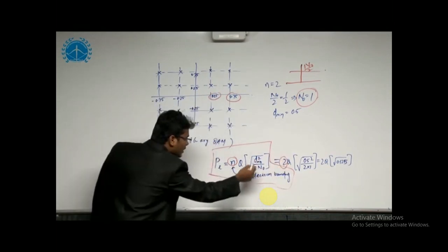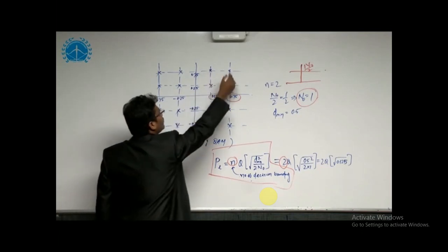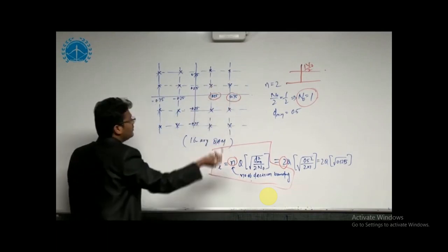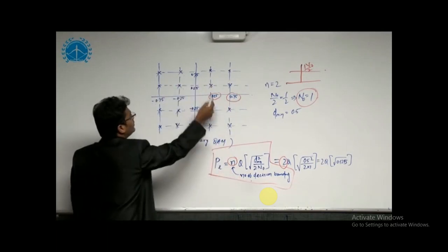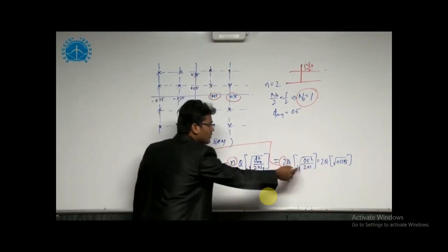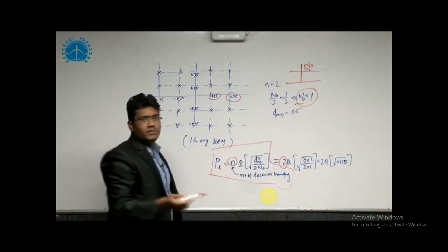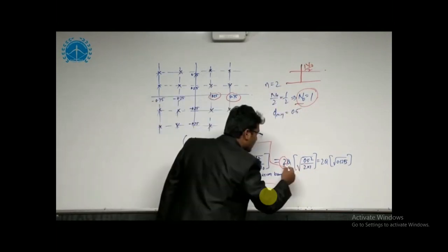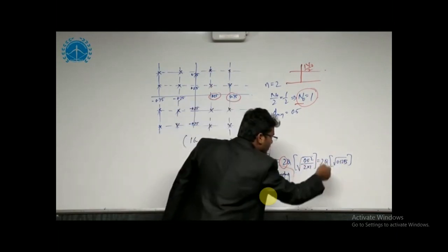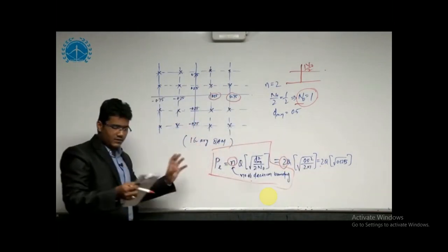So the value of d min I now have to find. What is the d min value? The minimum distance between two levels. You can see here 0.25 to 0.75 is 0.5. Otherwise, you can take minus 0.25 to plus 0.25, which is also d min. I can take 0.5. So now I substitute this value, 0.5 square by 2N0. N0 I already got as 1, as it is the given white noise power spectral density. So my answer is 2 of Q, if I substitute 0.5 square by 2, so I get 2 into Q of root over of 0.125, which is my probability of error, and the option is option C.